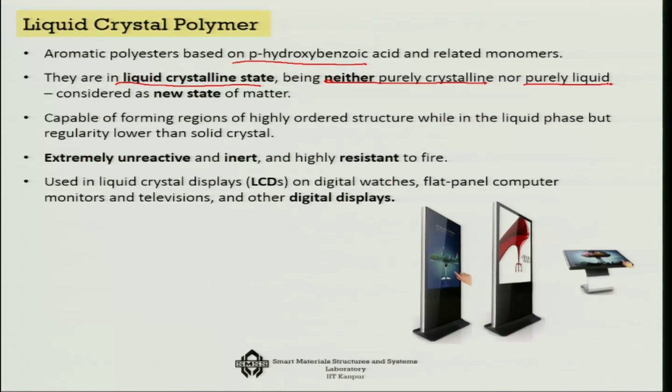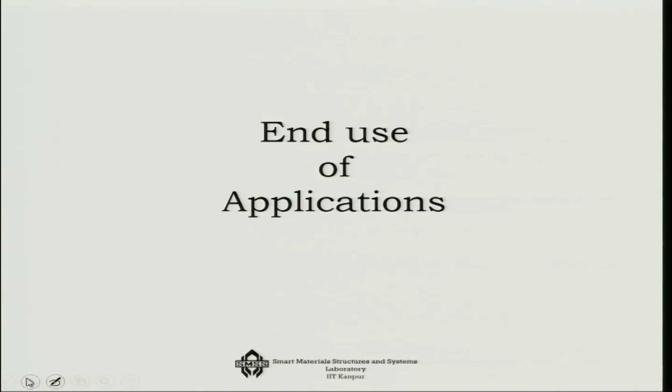They are capable of forming regions of highly ordered structure while in the liquid phase, but with regularity lower than the completely solid crystal. They are extremely unreactive and inert and highly resistant to fire. Something like your LCDs, the liquid crystal displays on digital watches, flat panel computer monitors, televisions and other digital displays, are actually made of these liquid crystal polymers.